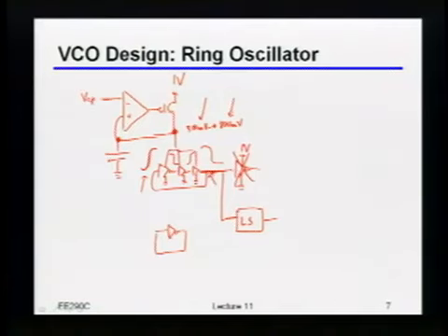Source follower. Remember, I'm trying to go from a variable low voltage to a single fixed high voltage, so I'm not sure how I could do it with a source follower. You have a cross-coupled PMOS, two NMOSs at the input. Okay, you said cross-coupled PMOS.